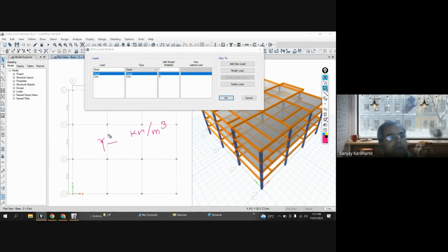For concrete, you are assuming 25, then for any other, you may go for 20, let's say mortar or brick masonry, etc. If you follow IS codal provisions, under IS 456 part 1, you will get the wet density of various materials that are applied in civil construction, right? There, for concrete, you know that the wet density is considered as 25 kilonewton per cubic meter. Now every element.